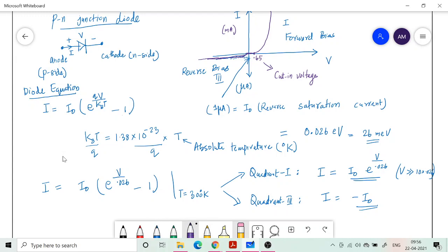One more thing I would like to say is that the voltage that you vary here, you vary in fractions of a volt. You don't vary like 1, 2, 3, etc. When you forward bias, you can't do that, because the current is going to rise very rapidly according to the forward bias quadrant 1 relationship, and that will tremendously increase the current, and we need to limit the current to say less than 50 milliamperes. Therefore we cannot apply any voltage greater than 0.75 or a maximum maybe 0.8 for a silicon diode. For a germanium diode it may be a different value.